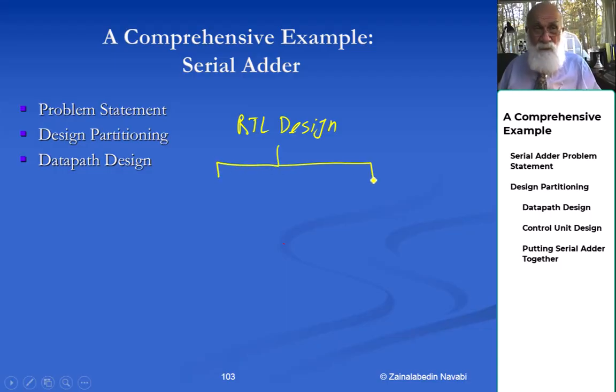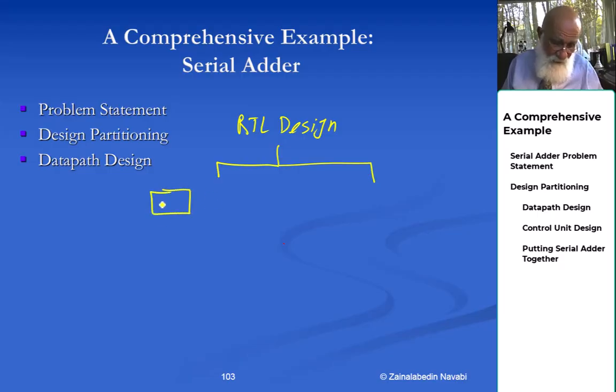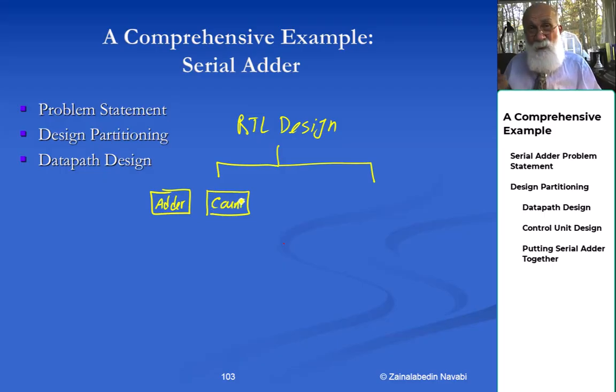For example, if you're doing a multiplier, you say, well, multiplication is done by adding, so I need an adder, a combinational adder. Then you say, at one point I need to count some inputs, so you need a counter. Then you say, for a filter, for example, you need to save some previous data, and then you need a register file.